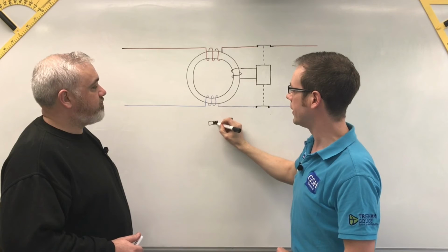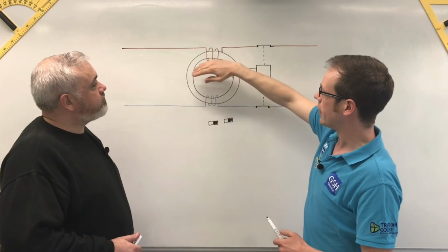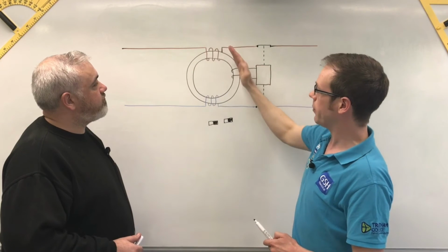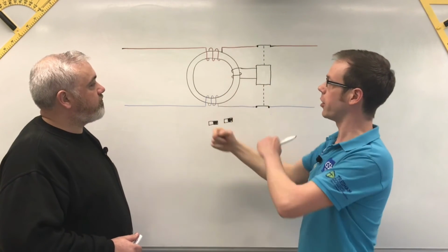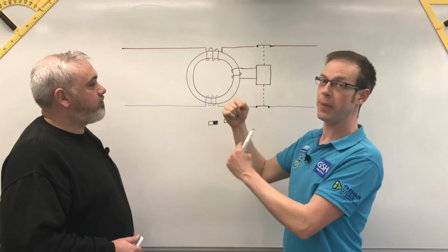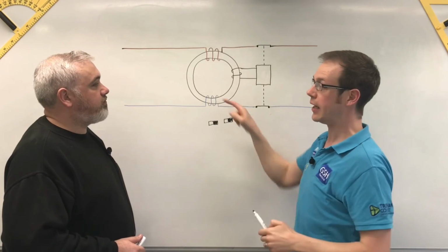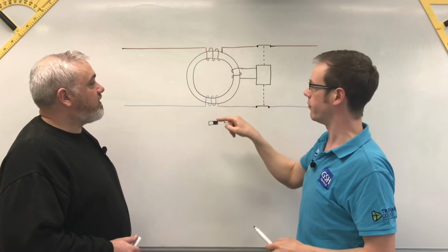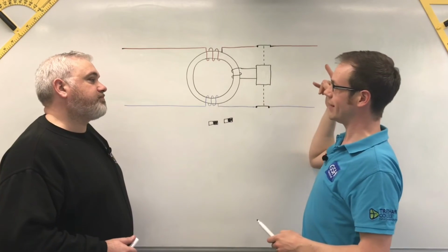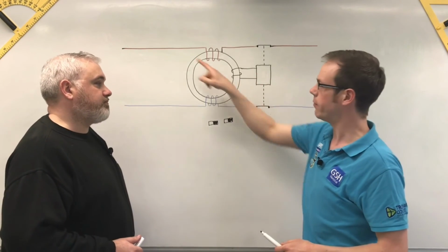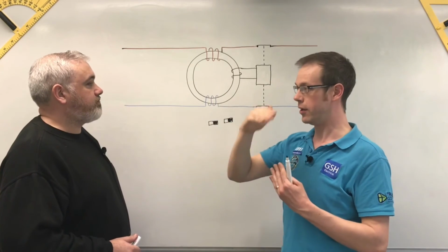Now when current is applied in the positive part of the cycle, the molecules all flip to follow the path of that magnetism that is applied to it. And then when the current changes direction, they flip back the other way again. They're constantly changing their polarity in line with the changing of polarity of the current flow. Now, the problem arises because we've injected DC back into this circuit, the positive part of the cycle becomes a higher current.